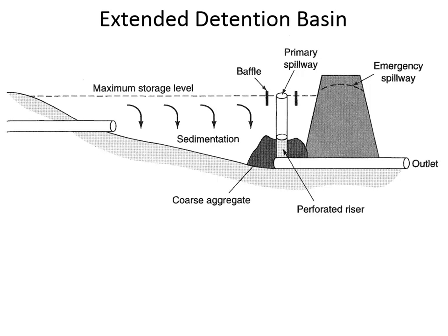And if we want to know Q, the flow rate that will come out, then we say it is the coefficient of discharge times the area times the square root of 2gh. And so the orifice equation governs the outflow from the outlet.